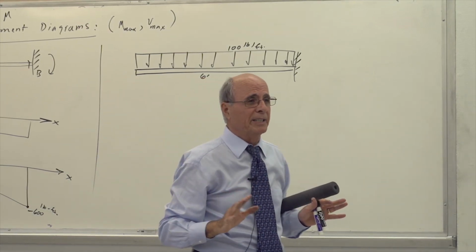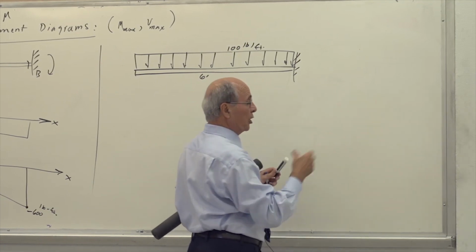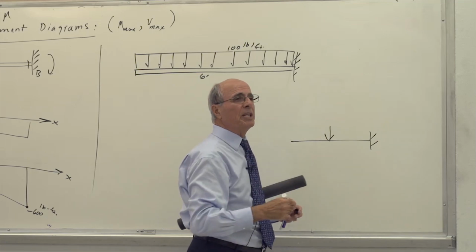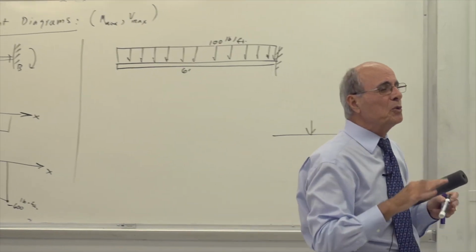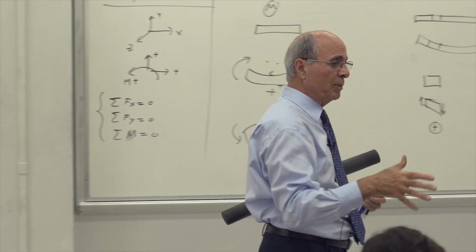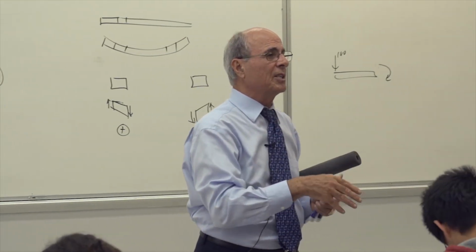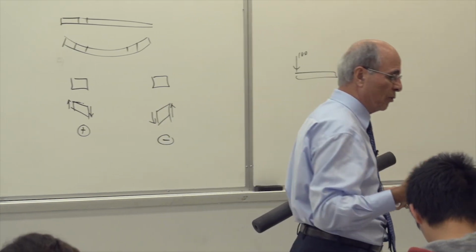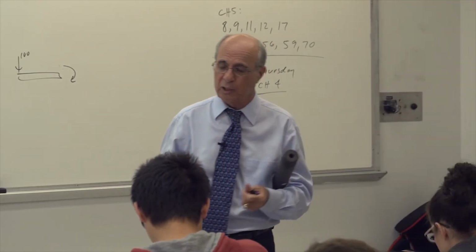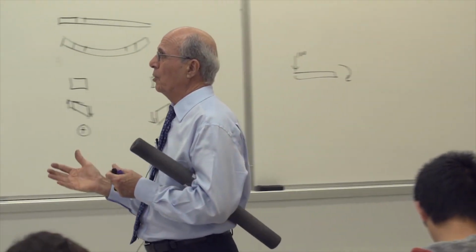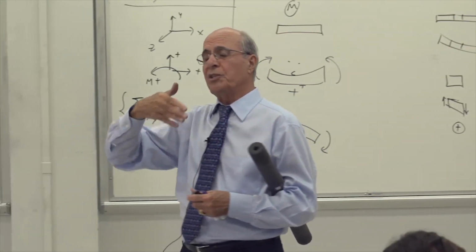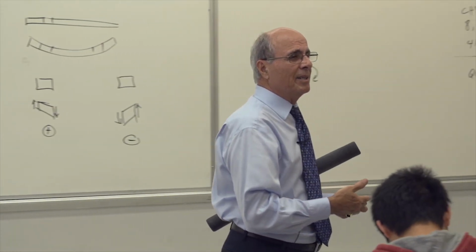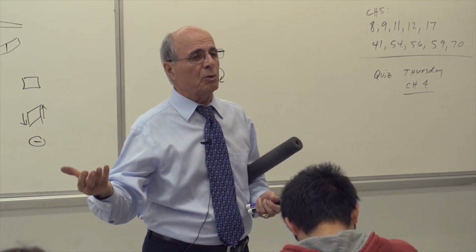However, look what happened here. If I change this beam, don't draw it, don't write it down, to this format, these two are not going to behave the same. So you cannot change it, write it down. For shear and moment diagrams, you cannot replace a uniform load with a single load. You can replace a uniform load with a single load to use the statics for finding the reaction, but you cannot draw shear and moment diagrams with it.